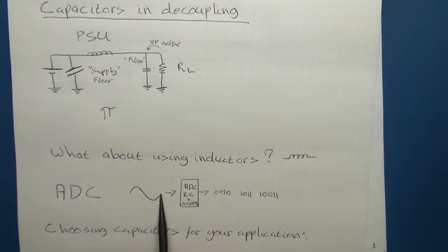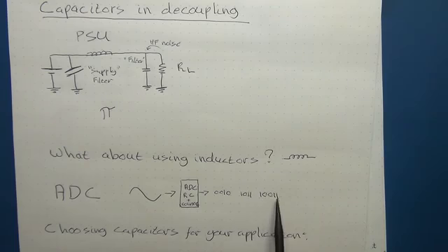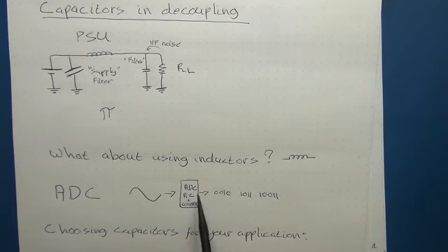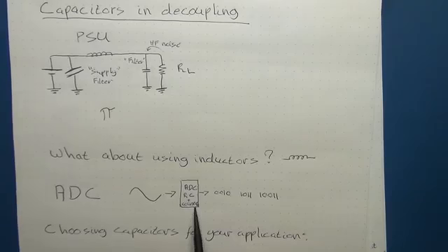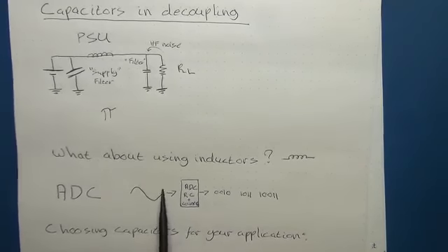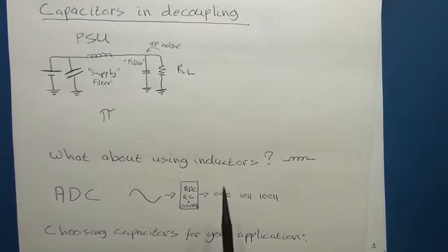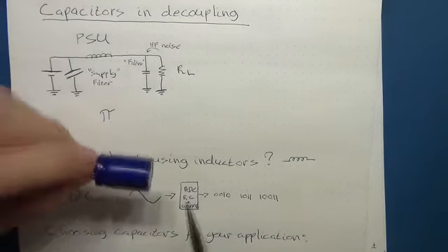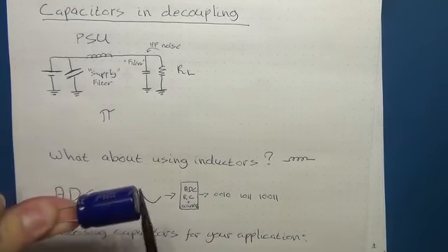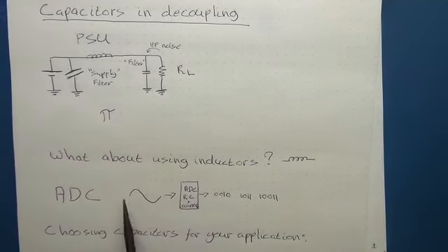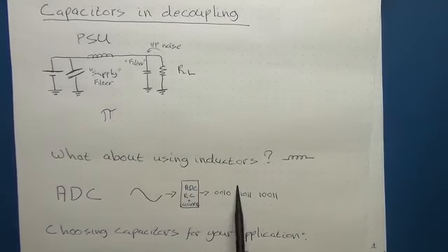If we have an analog signal coming out, and obviously we're expecting a digital output, the RC time component of a capacitor is used in conjunction with a counter to basically take levels and then get your digital reading out. Now it really is an oversimplification, but when you start looking into how ADCs work, you'll realize how the role of a capacitor is critical as a timing device, which leads us in from the analog world and into the digital world.